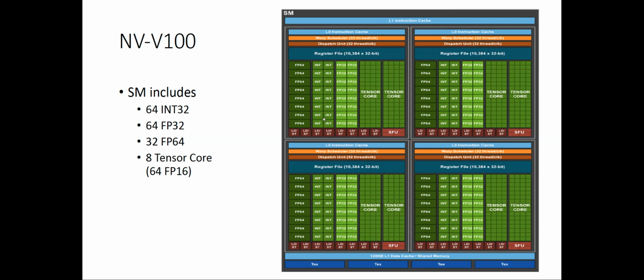For example, the tensor core is one of the architecture contributions introduced in AI ASIC cores this year: we build a very customized tensor core unit just to accelerate certain types of data. Here in this case, that's floating point 16, because floating point 16 provides higher computation TFLOPS and higher computation intensity compared to floating point 32, but maintains similar training accuracy in most deep learning models.